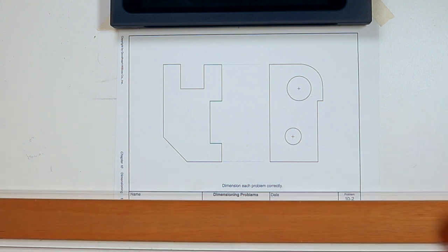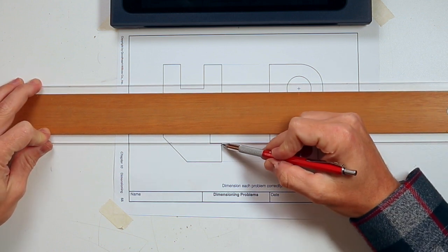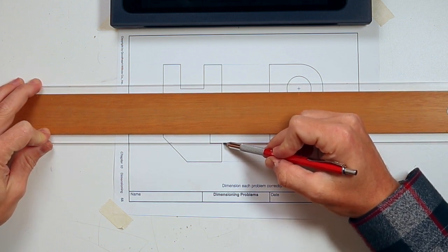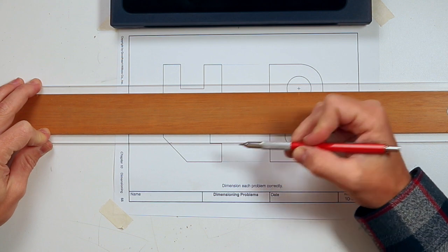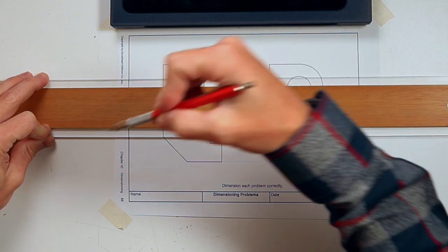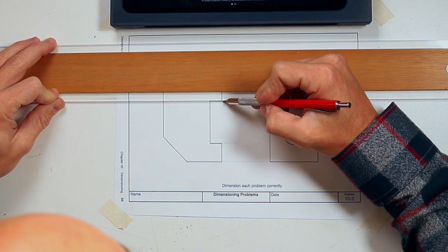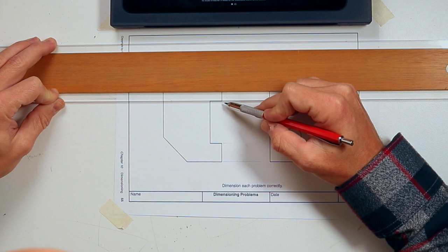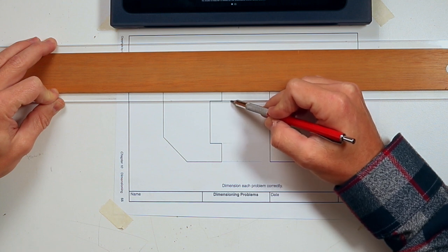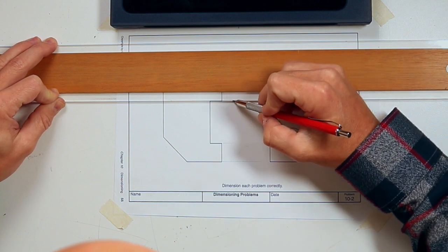From here, I can go ahead. I'm going to refer to these little tick marks I have. I'm going to extend off of this first part because this is going to be my first dimension. I'm going to move up. I don't need the angle because I'm going to be putting it on the left-hand side. Now I need this dimension. Leave that 16th inch gap from your object, and I'm going to extend right above that tick mark. So you can overdraw the extension because you can erase later.